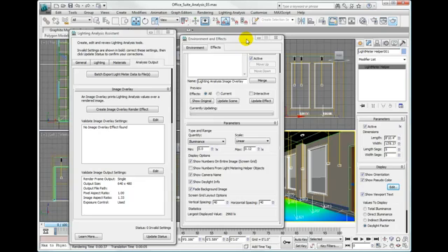render effects parameters rollout, we can see the largest displayed value was 2,714 lux. Let's go to our max value and type that value in. So 2714 and hit enter. Now we'll change our light meter color coding because that's no longer set.